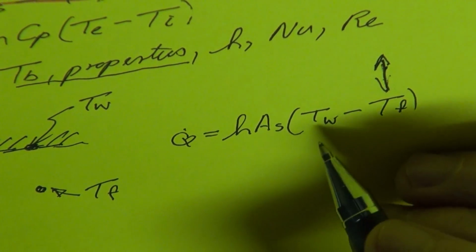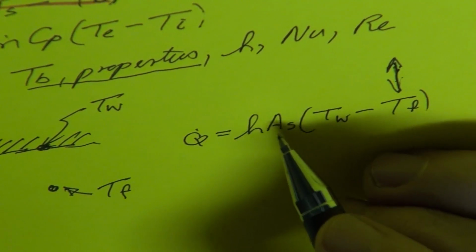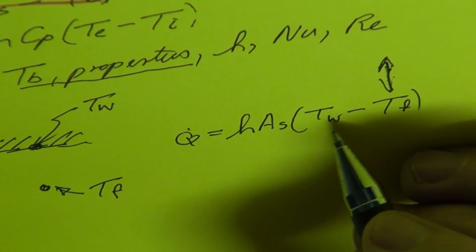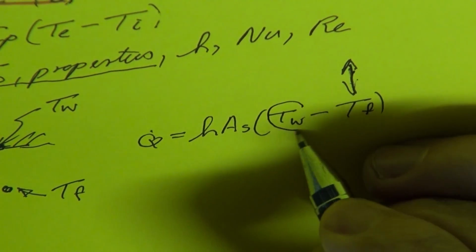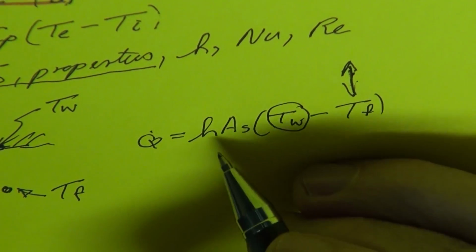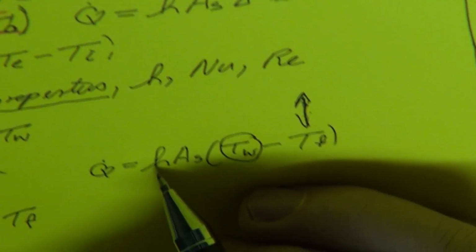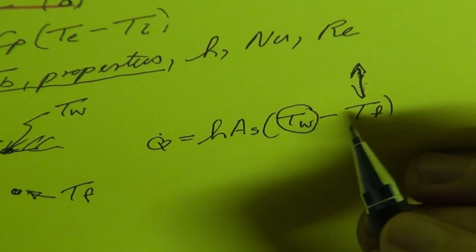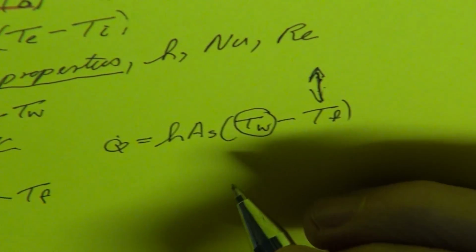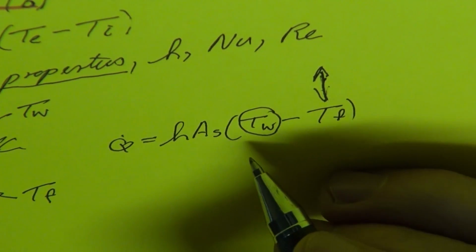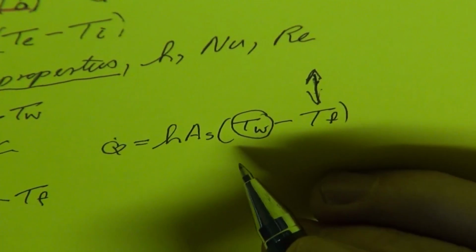Okay. While the surface obviously is known, what helps in this case is that the wall temperature is constant, but the heat transfer coefficient is not necessarily a constant. So we have things which are changing, and that is what makes internal forced convection a little bit more complicated.